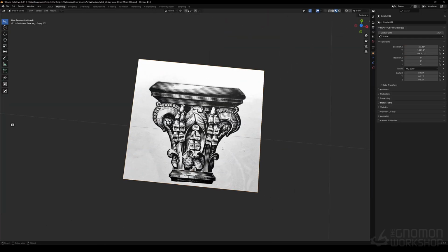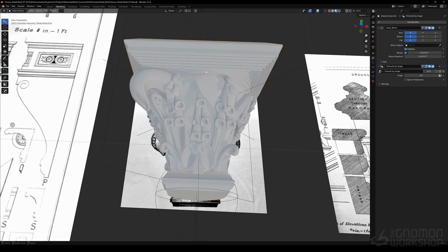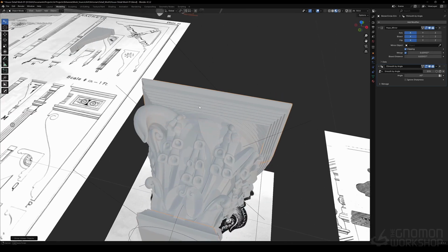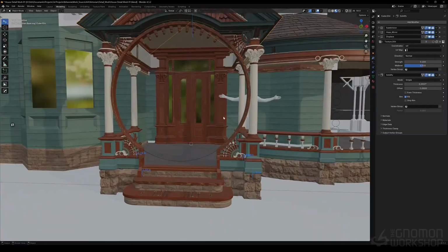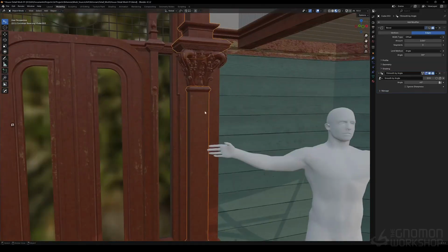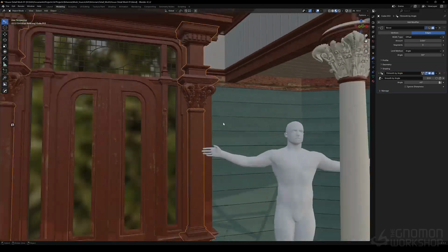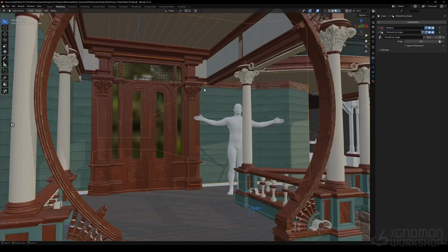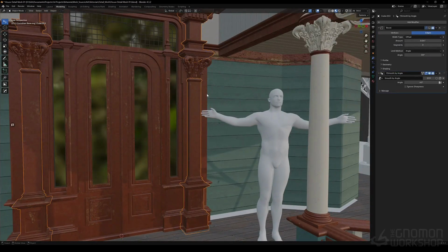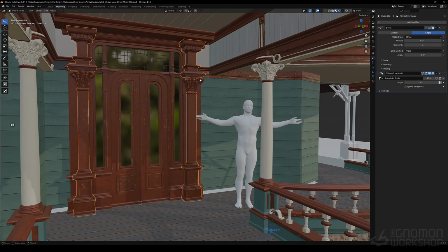With this design, again, because it's the Victorian vernacular, they're doing things a little bit differently. This one has a circular abacus at the top, so I put that in here too. And then I left this square abacus for my pilasters. And a pilaster is basically the part of a column that is squared out and then is embedded into a wall to reference the concept of a column holding up a beam above. But generally, pilasters aren't always structural. They are decorative to inform the idea that they could be structure.